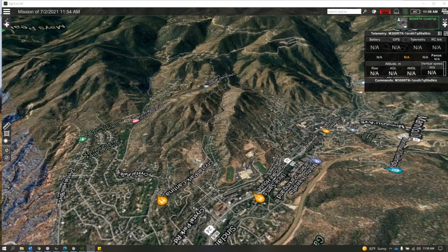Hello, today I'll be making a video on how to generate a flight plan in UGCS so we can utilize the desktop planning features along with the built-in terrain following, which is key to successfully collect accurate and consistent data. I'll specifically be planning an area map mission to be flown with the DJI M300 and a third-party LiDAR sensor such as the YellowScan mapper.